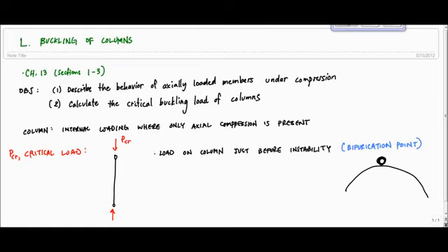It's this bifurcation point. And for us right here, if our P applied is less than the P critical, then we're stable. We have stable equilibrium. And if our P applied is greater than P critical, then we have an unstable condition. Okay, instability. That is essentially a boundary for us in terms of loading for a column, or a compression load. Okay, this is a compressive load.